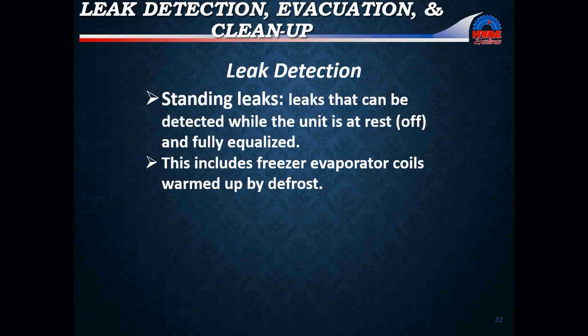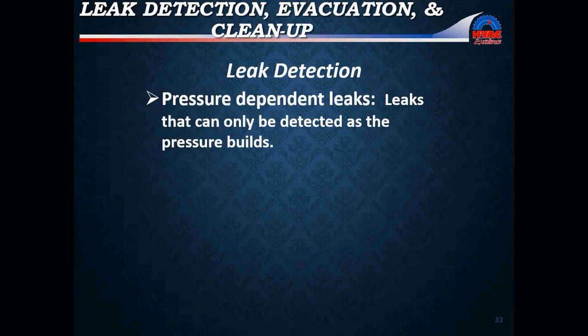So we have different ways of leak detection, and the first one is the most common, and that's your standing leak test. Okay? Standing leaks can be detected while the unit is at rest, or it's off and fully equalized. This includes freezer evaporator coils warmed up by defrost. Standing leaks are the most common type of leaks that we can possibly see.